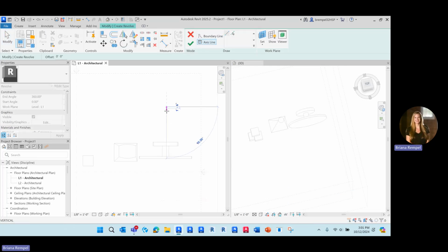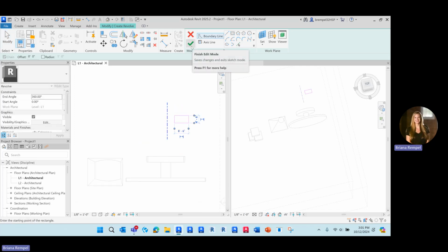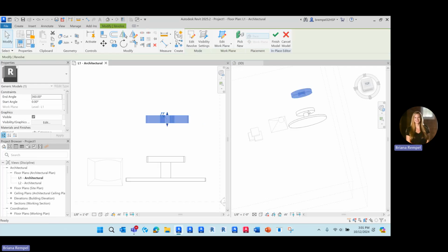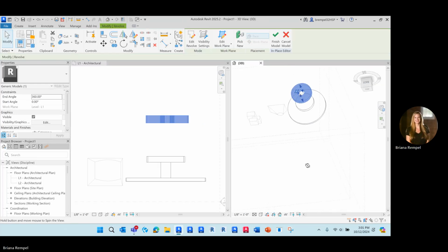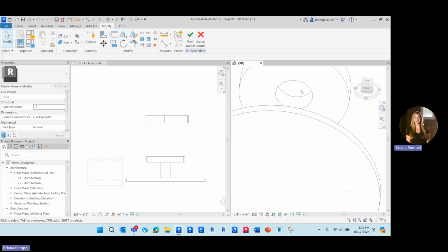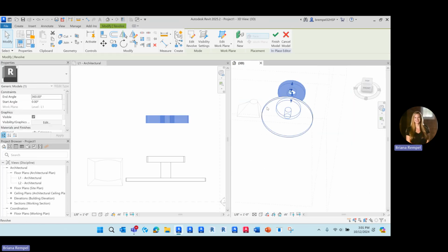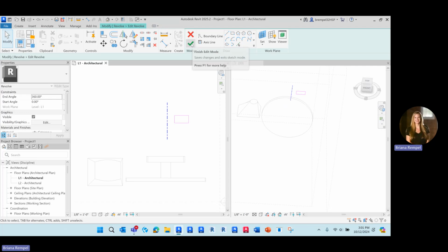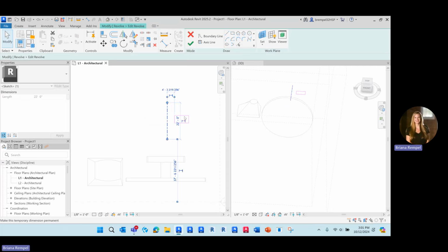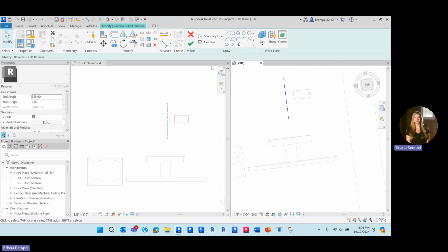So if I put my axis line here, if I were to draw something not touching the axis line, this should just look like a big donut, right? And there we go. So you can have that hole in the center by adjusting how far that is. If I need to adjust it, I can always come back in and edit that revolve. So you can just start to visualize, in 3D, this profile wrapping around this axis line.